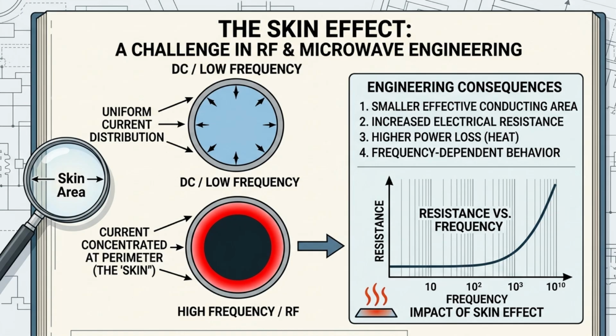This behavior creates an important engineering challenge. If most of the conductor interior carries little current, the effective conducting area becomes smaller. This increases resistance and power loss, making conductor behavior frequency-dependent. Understanding this effect is essential in RF and microwave engineering.